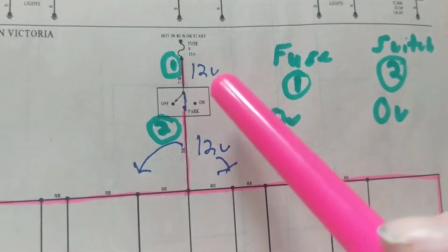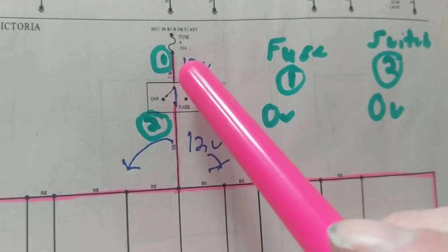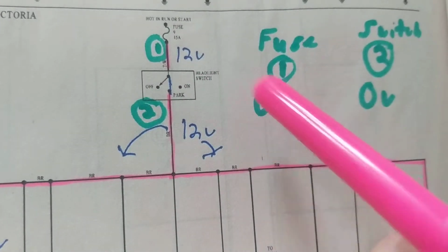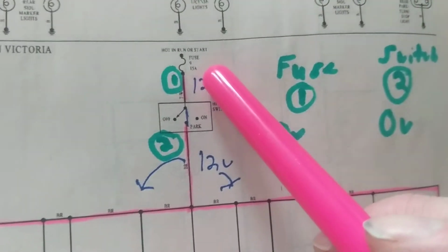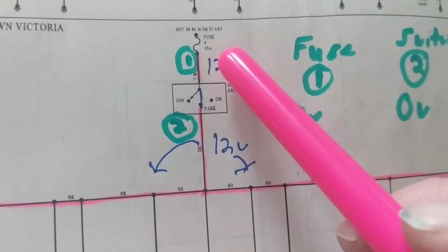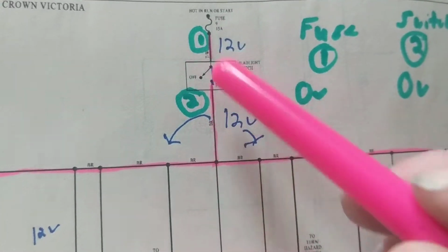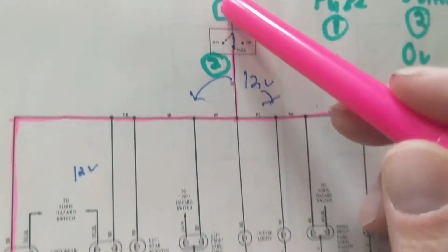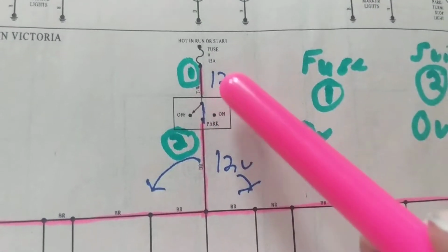If the fuse is bad, I go at one side, it's 12 volts. I go at the other side of the fuse. If it's open, you get 0 volts. Therefore, we know the fuse is the problem. However, what are we going to do? We're going to put another fuse. Well, let's say there's a short to ground. Let's say there's a short from here to here. So I'm going to keep on putting fuses and blowing fuses?